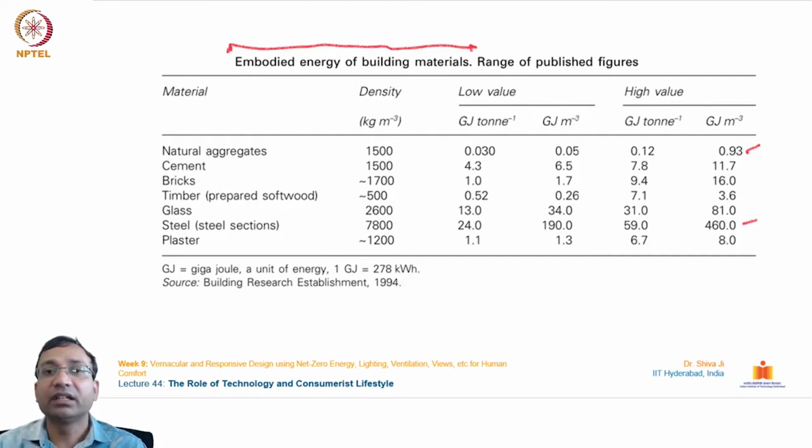You can utilize the lessons from this lecture and this course in your design projects and exercises. How well or how efficient you can make them by just changing, for example, just the material part of it. Instead of using bricks, if you use adobe-based bricks or rammed earth bricks, how much energy, how much embodied energy can you save right there.